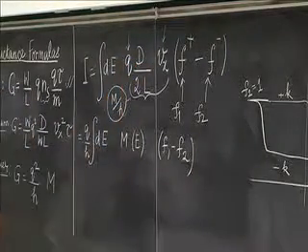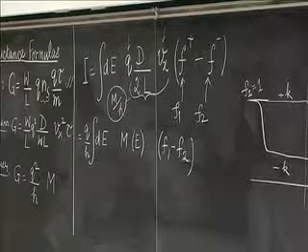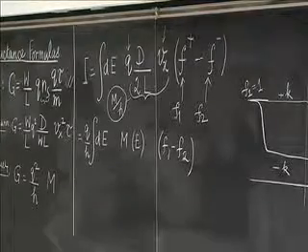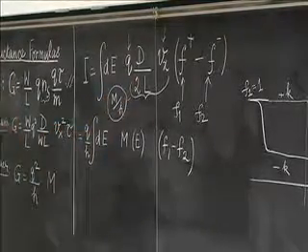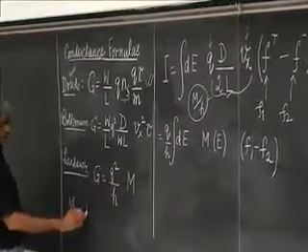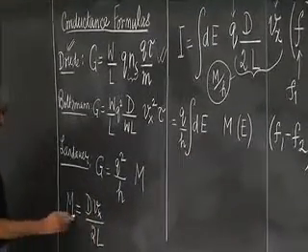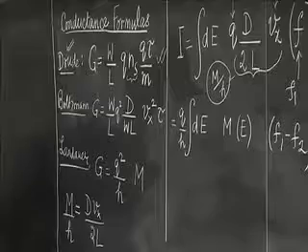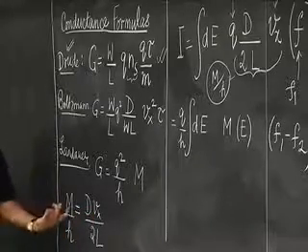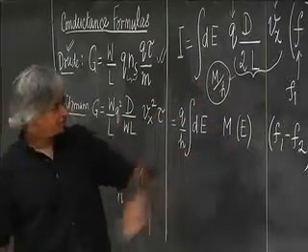So just as density of states determines electron density, when you want to calculate current, you need density of states times velocity. It's not enough to have a state there. It has to be moving. So that's why this is dV. So the expression for M then would be something like dVx over 2L. This is M over H. It's just dimensionally, this has the same dimensions as H. M is a number. It's a constant. So instead of that quantity, I've written here M.